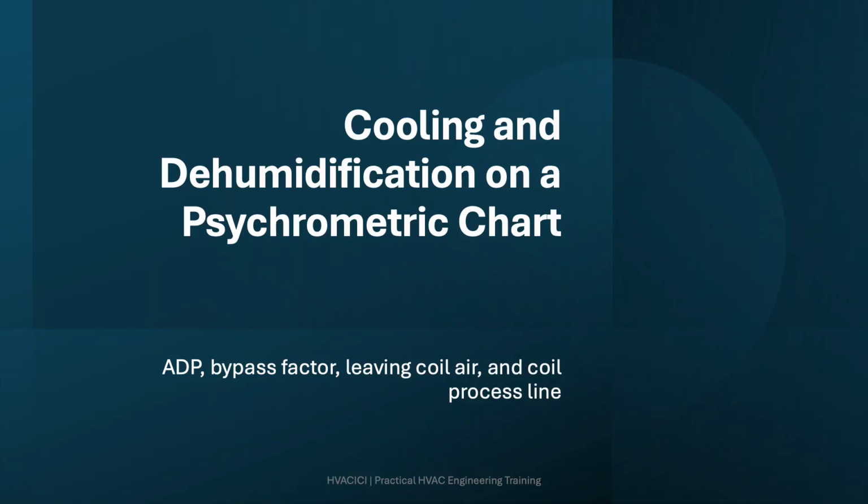In this video, we will review cooling and dehumidification on a psychrometric chart, focusing on the cooling coil process line, apparatus dew point, leaving coil air, and bypass factor.